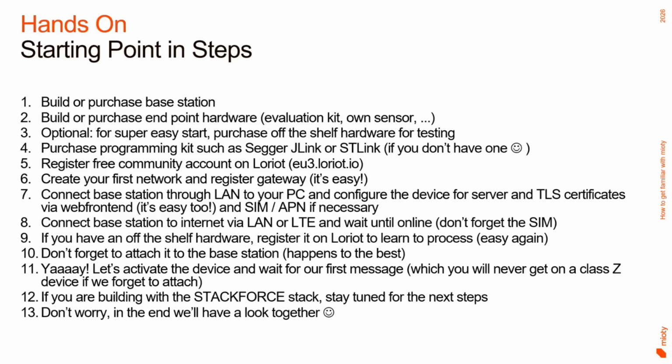Then it's really easy. You will need to configure the gateways. All of the off-the-shelf gateways that you can find on the market offer some sort of web interface that you can connect to your PC's LAN, configure it, fetch the TLS certificates, and then you're ready to go. You just connect your gateway to the internet with LAN or LTE. You might have to insert your own SIM, and then your network should be set up.